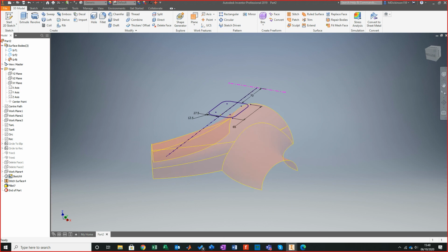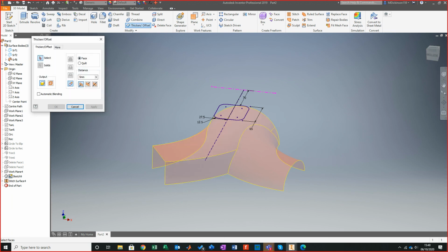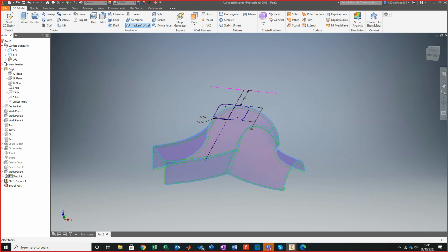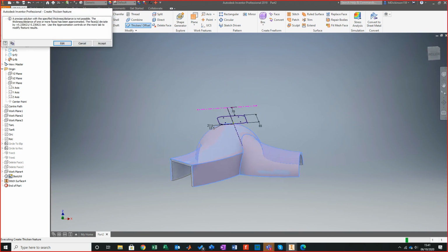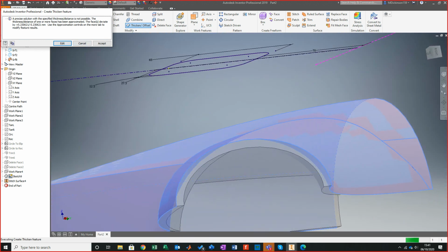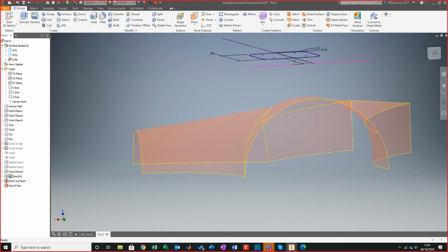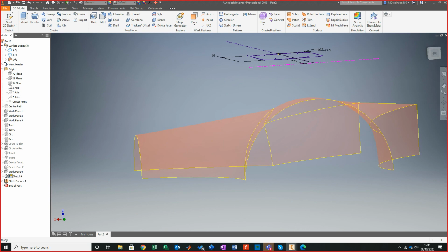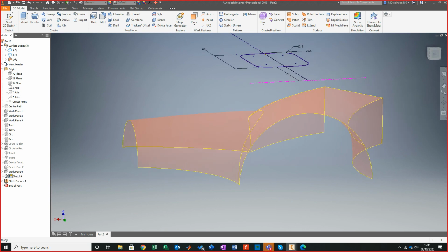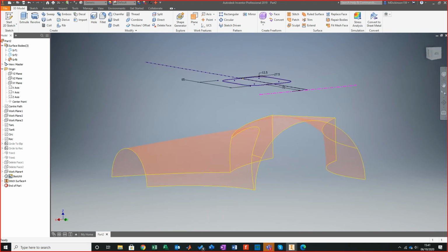So if I just go back to this and delete that out, I go back to this and delete that out. Now the interesting thing is, if I thicken that component now, bring that in, thicken it, and then click OK, what it should do is still have an issue across that back plate. That's a really odd one. So that would suggest that the loft itself was problematic. How is that so problematic?